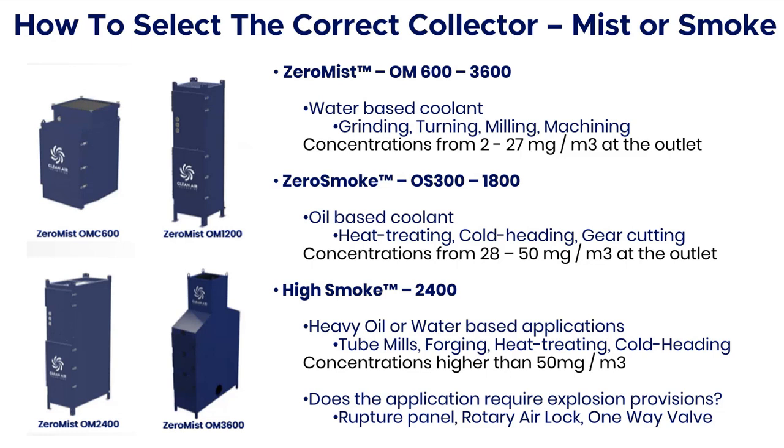What we do is we bring what some people call a sniffer, but it basically tests a sample of the air, and it allows us to see how much concentration is coming out of either the outlet or in the operator position. I usually take readings in the aisleways, and it gives me a good idea of where the problem areas in the plant are. Number two, if there's a slinger on there, I will literally put the tube in the outlet and measure what the concentration is coming right out of that machine.